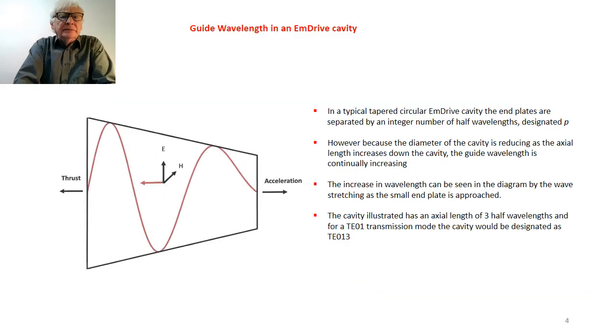The diagram illustrates a typical tapered EmDrive cavity, and in this case the end plates are separated by an integer number of half wavelengths, and that number is designated P, and the fact that there is an integer number of half wavelengths means that the cavity will actually resonate.